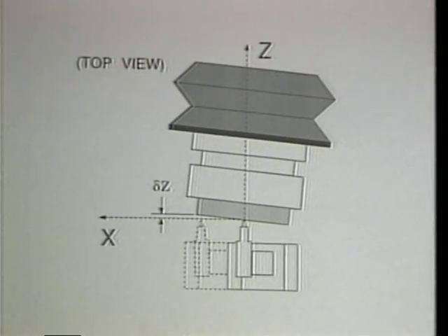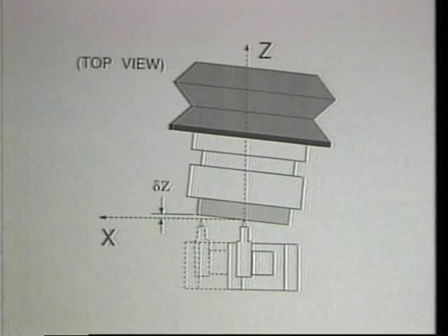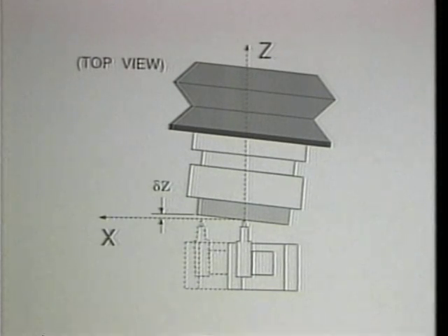But note that even for an Abbe offset of 0, z-axis error would result when the tool moved radially away from the center of the workpiece. From these brief examples, one can already sense the complex nature of machine design when viewed from a metrologist's perspective.